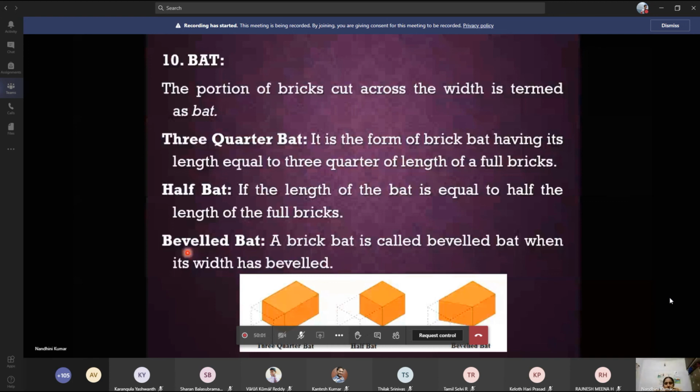If you arrange the bricks, one horizontal, one... Maybe for the joints, ma'am. Like if you are placing a horizontal column and a vertical column of bricks, for the joints to be perfectly perpendicular, they do it. Yes, that's the main reason. Very good, your answer is right. If there is only a little space left, you have to break the brick into either 1/3, 2/3, or maybe half, depending on what you need. They'll cut it accordingly and use that to fill the space.